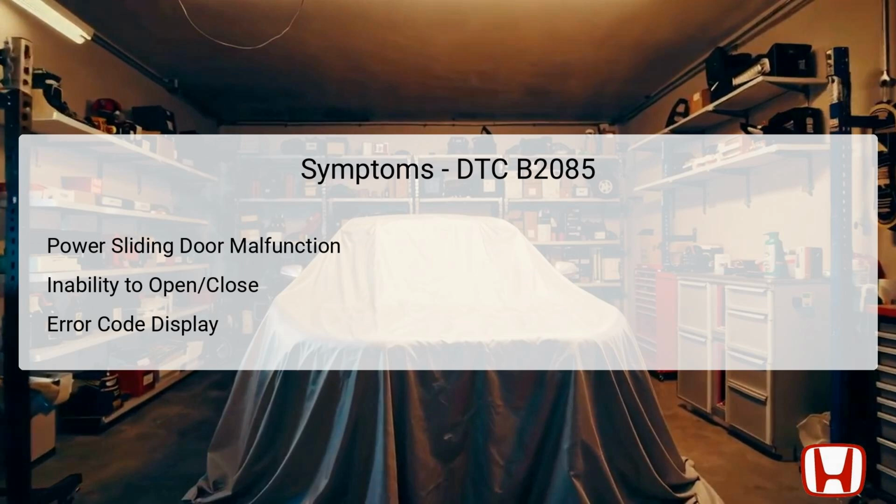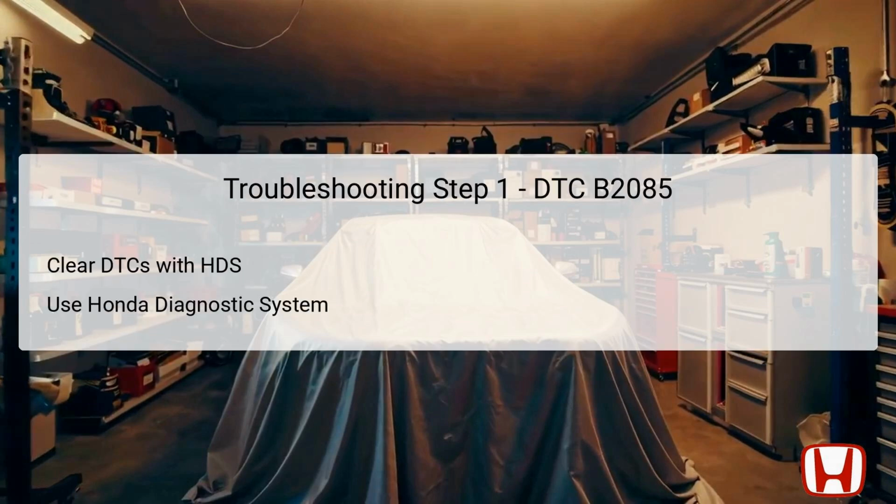The first step in troubleshooting DTC B2085 involves clearing the diagnostic trouble codes using the Honda Diagnostic System (HDS). This system is specialized software and hardware used to communicate with the vehicle's onboard computers, allowing for error code management and diagnostics. By selecting the option to clear the DTCs, you reset the system to gather new diagnostic data.